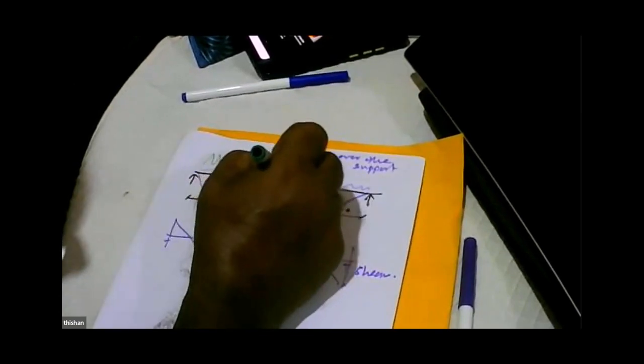And then you have the second load case where you put this as maximum, this as minimum, this as maximum. So what will happen? It will go like this. Then you have the third load case where you put this as maximum, others are minimum. Now you have an envelope.